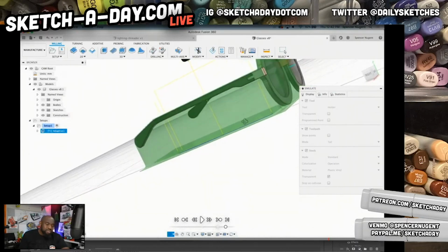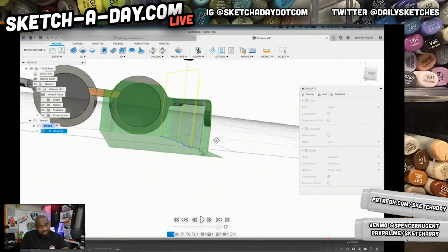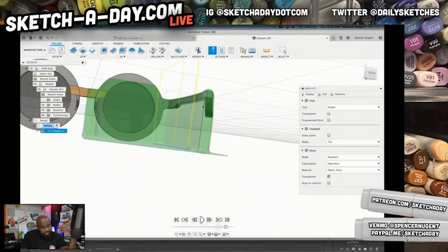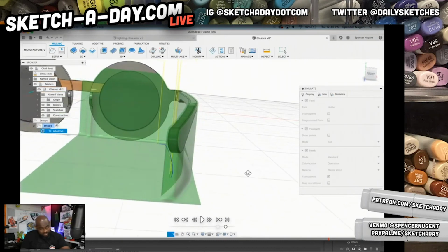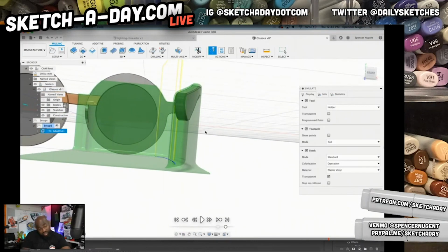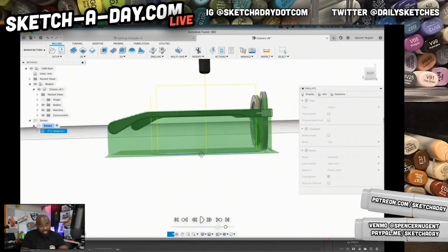Okay, so if you're machining stuff, and we can get into this another time, the tool is going to come in, that virtual thing that you saw come in, it's spinning at high speed, it's sloughing off material, it's cutting stuff away, and this is what you're going to be left with if you were doing a milling operation. So now you'd have to do another setup where you rotate this whole thing. You rotate it, and then the tool comes in another angle, or if you have a machine that can attack this at the right angle, that's what would happen.